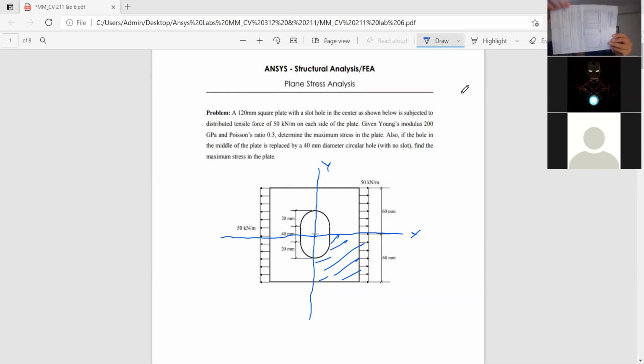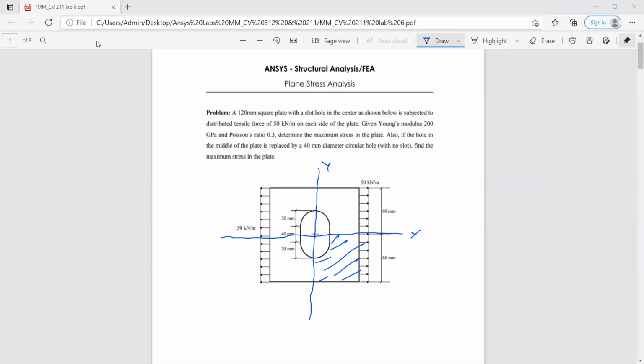When we mirror it, I mean we flip it so it looks similar to this. Or even better, we could fold it this way and then fold it this way, and now we just simulate a quarter. If we were to mirror it about here and about here, it would be the same thing as the full shape. That's fundamentally what I mean. And that's the process that we'll be using when we go about doing our simulation.